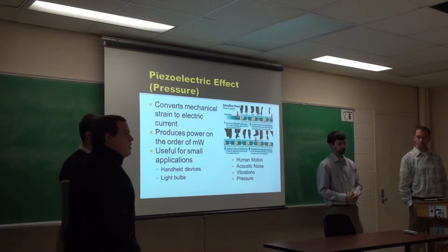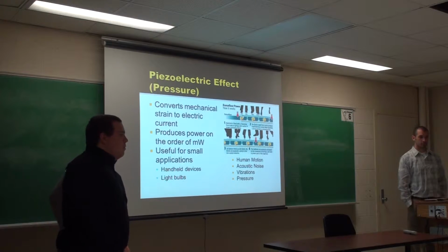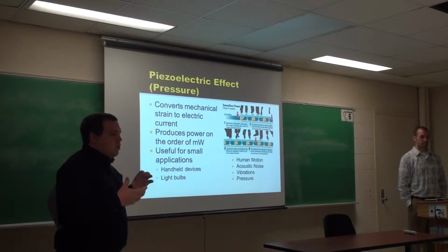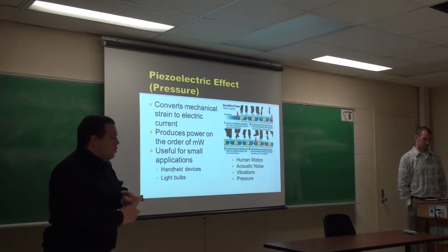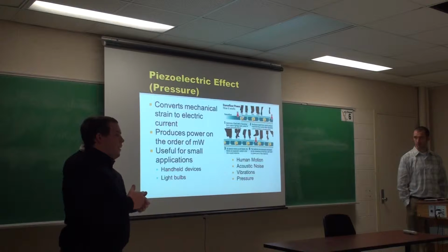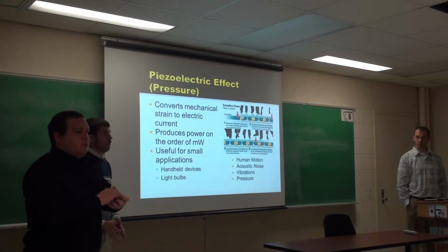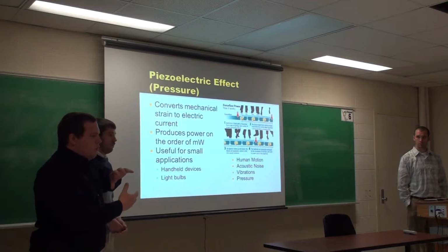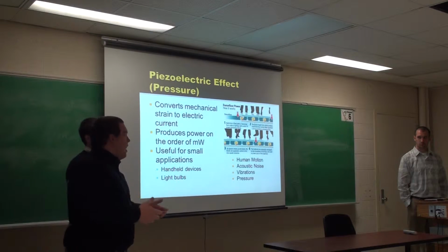The first way I want to talk about to harvest energy is the piezoelectric effect. Some of the teams are familiar with this, using it in their projects. It converts mechanical strain into an electric current, an electric charge that you can actually use. Some of that mechanical strain is human motion, acoustic noise, vibrations, and pressure. Piezo is actually Greek for pressure. It's taking the piezo material, crystal or ceramic, and squeezing and pressing it and getting an electric current out of it.